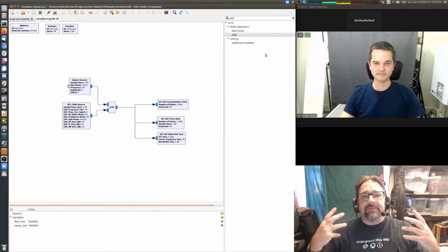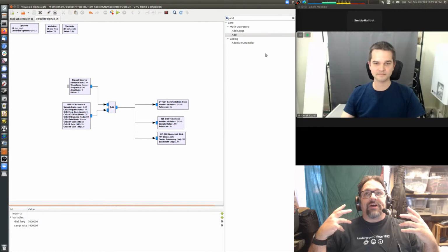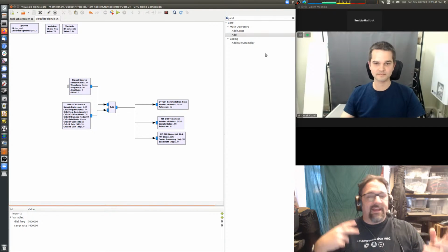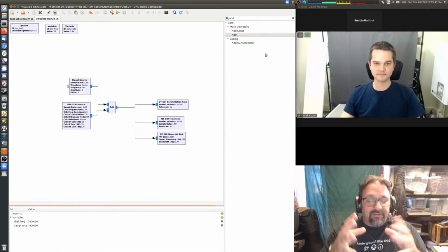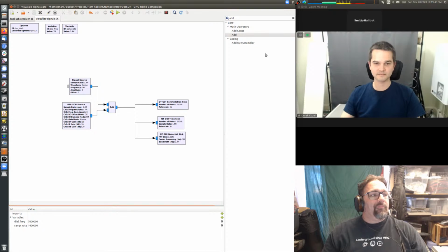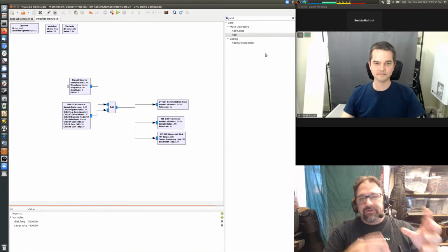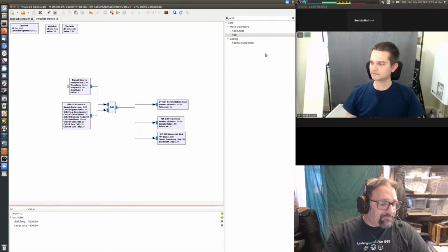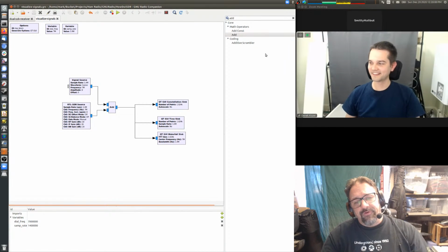But also sometimes you might use it to process audio signals like single sideband and AM, FM, to be able to do the filtering. And so there is no one definition of what is an SDR. SDR is just we take the electrical signals, we turn them into numbers, and we do math on those numbers at some point. And there are a lot of different ways of doing that.